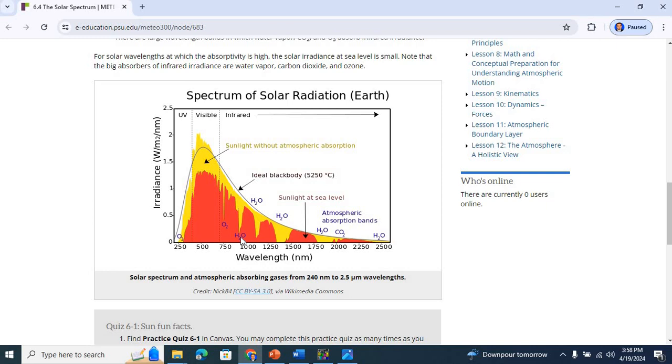Now, the path length of the light in the atmosphere depends on the angle, which will vary with the time of the day. And that is given by the air mass number, which is secant of the angle between the sun and the zenith, or between the light coming from the sun and the vertical direction. So we call it secant theta. So the air mass number is given by AM = secant theta. Now AM0 represents the solar spectrum outside the Earth's atmosphere.